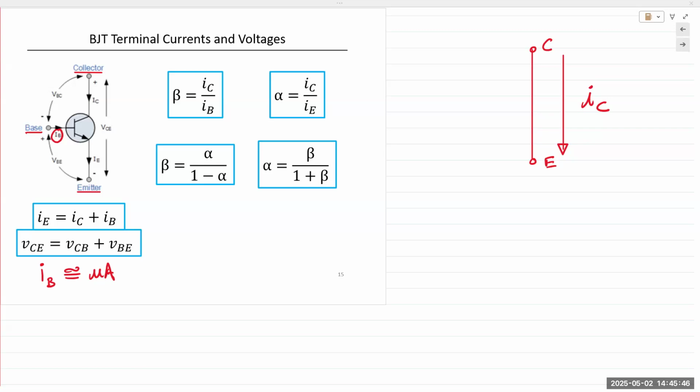It's also known as a buffer amplifier or an isolation amplifier, where the voltage is not being amplified, but the current is amplified in a sense. It's to avoid something known as the loading effects. You don't want the load to pull in a lot of current from the input, which would not be able to provide that anyway.